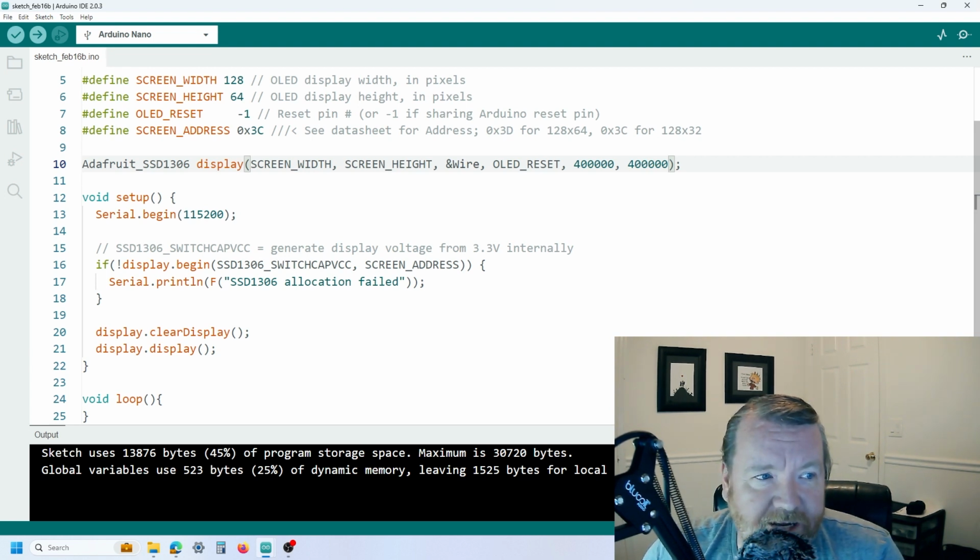Now, the key takeaway is you've got to be careful. I did a bad thing. I was assuming that the command wire.setClock worked. It's only because I happened to use the scope to actually look that I found out that it wasn't actually doing what I thought it was. So the key takeaway is just be careful. That's all of the warnings I can give you.